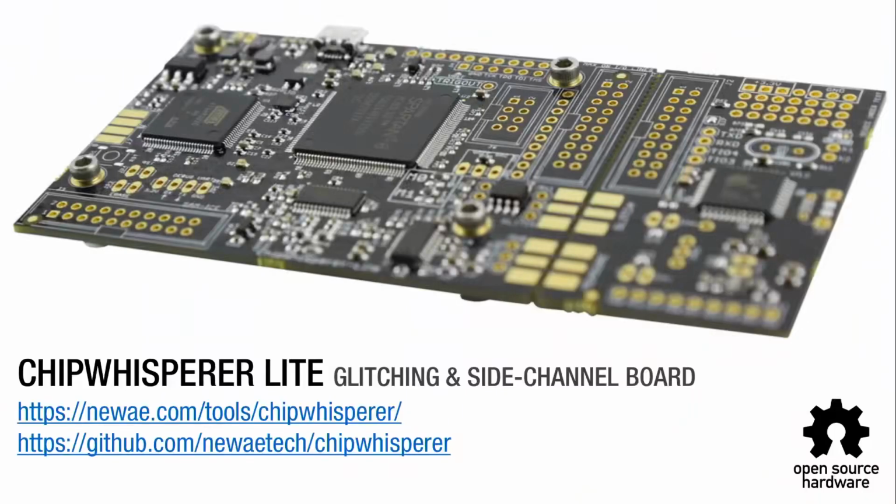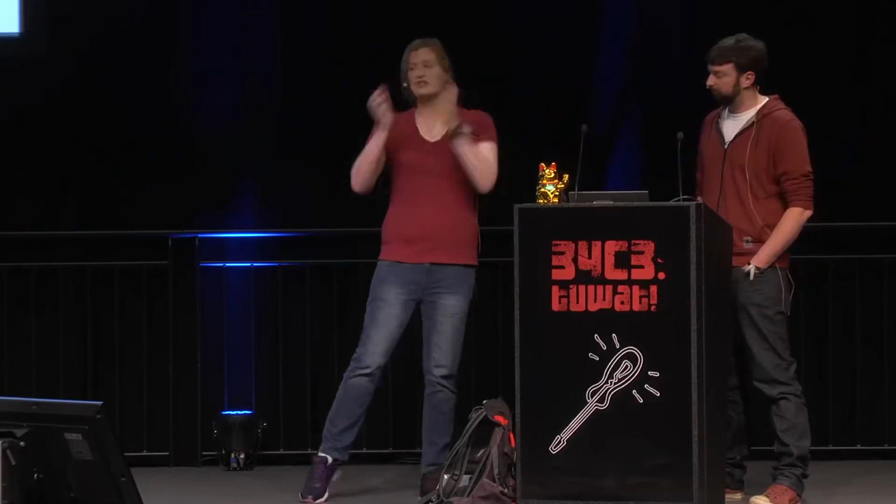Describe the ChipWhisperer. So one of the foundational pieces of technology we are using, we're basing a lot of our work on, is the ChipWhisperer. So picture it as the ChipWhisperer Lite, which is the inexpensive variant of Colin O'Flynn's glitching toolkit. And this is a toolkit that lets you do some power side channel analysis and some basic glitching attacks. It has modules for clock glitching and for power glitching, so we can implement both of those two kinds of attacks. And it provides software and firmware on a microcontroller and FPGA that are designed to let you precisely time glitches relative to some known synchronization point.